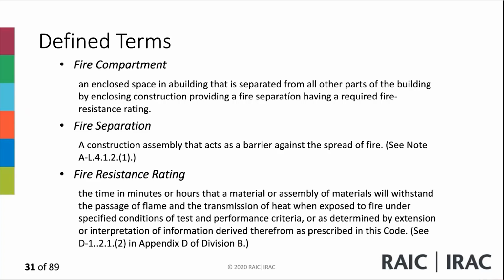Okay, the fire performance limitations, interpretations of test results. The fire performance ratings set out in this appendix are based on those that would have been obtained from standard methods of the tests described in the code. The test methods are essentially a means of comparing the performance of one building component or assembly with another in relation to performance in fire. So when we're conducting fire resistance testing, we're comparing. It's a basis for comparing the different assemblies.